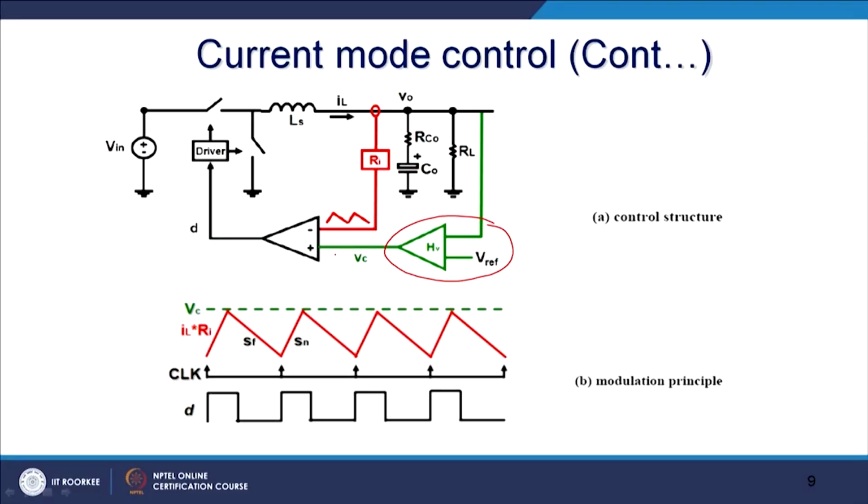and thereafter you will be sensing the current. It can be sensed by a resistance with a very low value of inductance, or by a Hall effect sensor, and that you put in, and ultimately you will have a comparison. So, you are allowing the current to grow, and you have a scaling network, and accordingly you require to scale it. So, it will be compared.